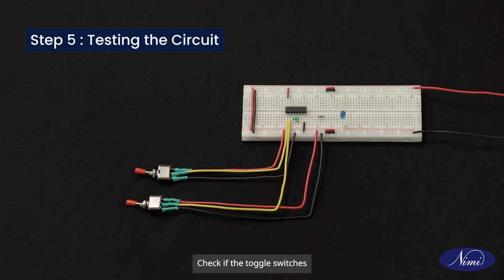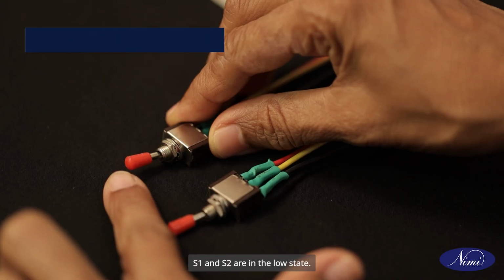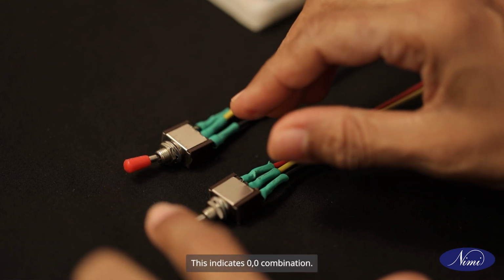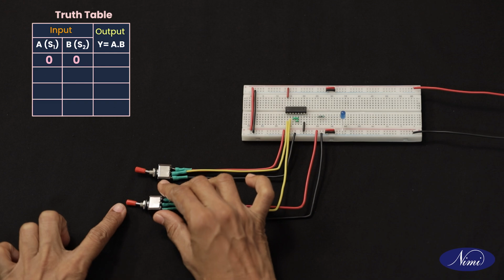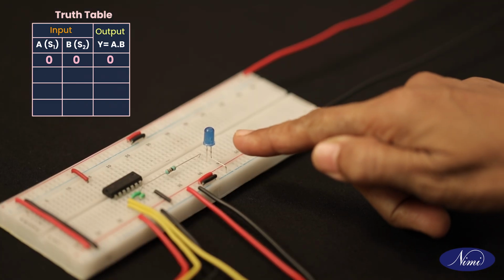Begin the test by operating switches S1 and S2. Check if the toggle switches S1 and S2 are in the low state. This indicates 0-0 combination. For this, let us verify the LED. It is not glowing.